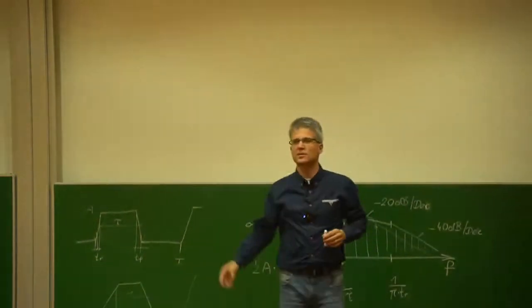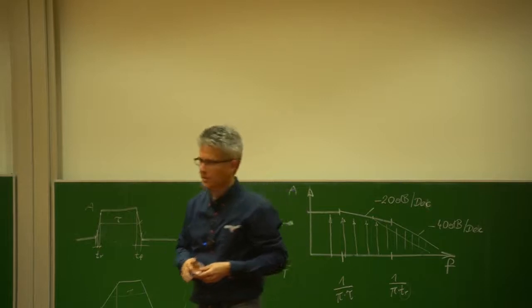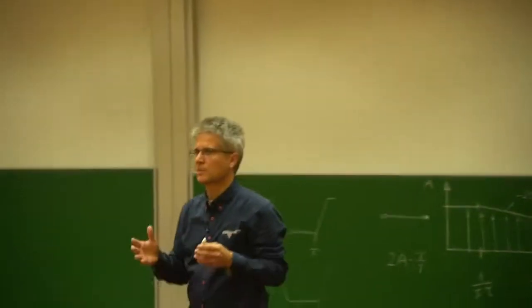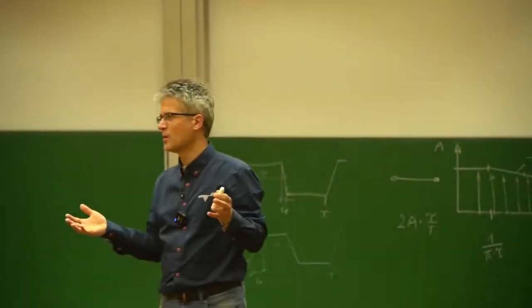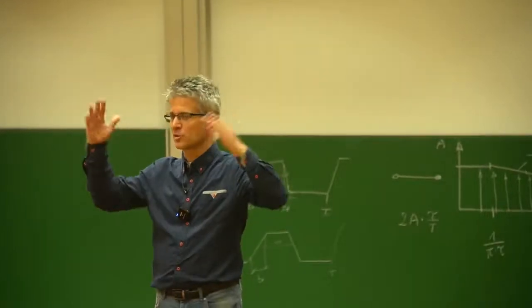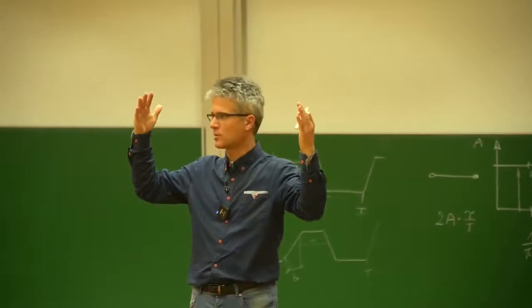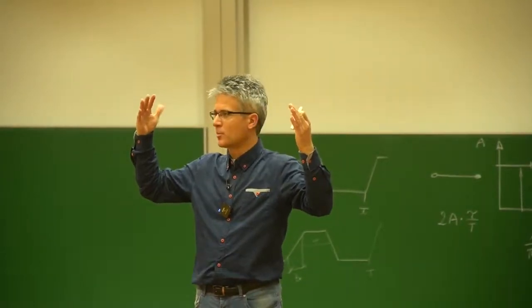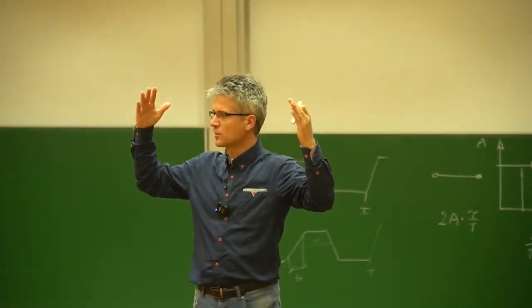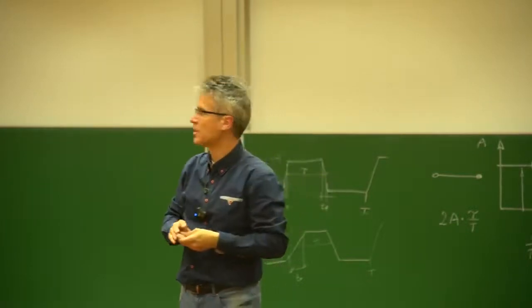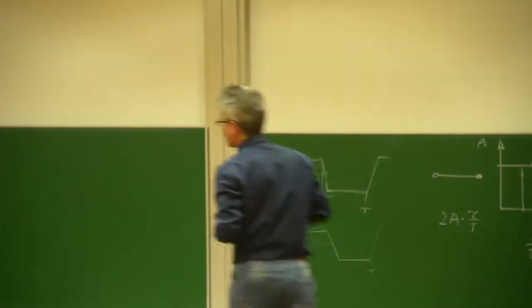And this is exactly the second thing that can be done. We can design a CMOS output driver where we can adaptively change the rise and fall time. If we need a very high-speed signal, then we can make the rise and fall time very small. But if we have to reduce the electromagnetic emission, then we can step by step increase the rise and fall time. And this is exactly what I did in my chip.